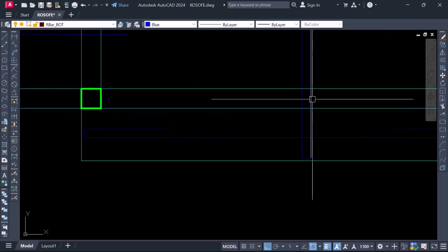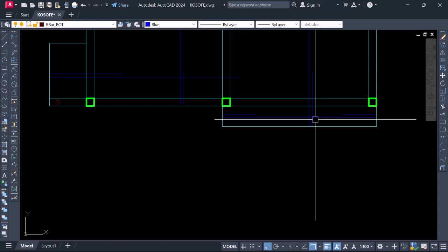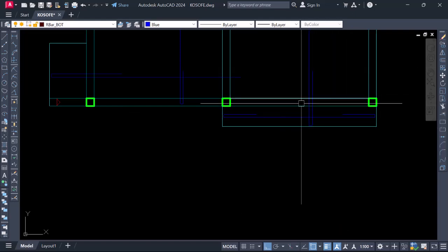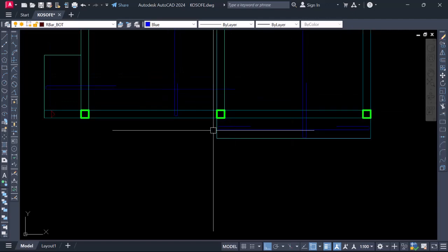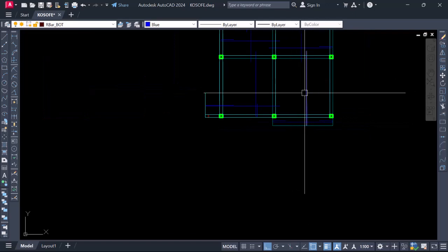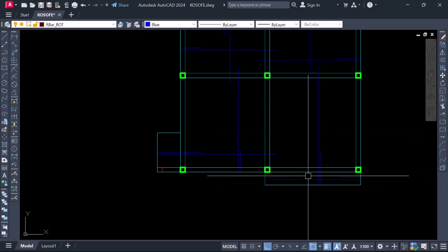I'll return down to the beam and extend. That's when we now begin to count our top bar. You don't count the top bar here because we are at this area. We're considering this to be a cantilever. So we are stressing all of the load around this area down to this panel, because it's a cantilever. We are returning everything down to this beam.